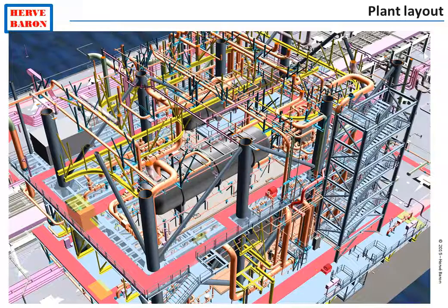In fact, the equipment layout for offshore facilities is strongly determined by maintenance requirements, by accessibility for maintenance. Indeed, overhead access with a crane for removal of parts is not feasible offshore as it is onshore, as equipment are stacked on several levels. Therefore, parts must be moved by means of monorails to the edge of the platform where they can be picked up by the crane.